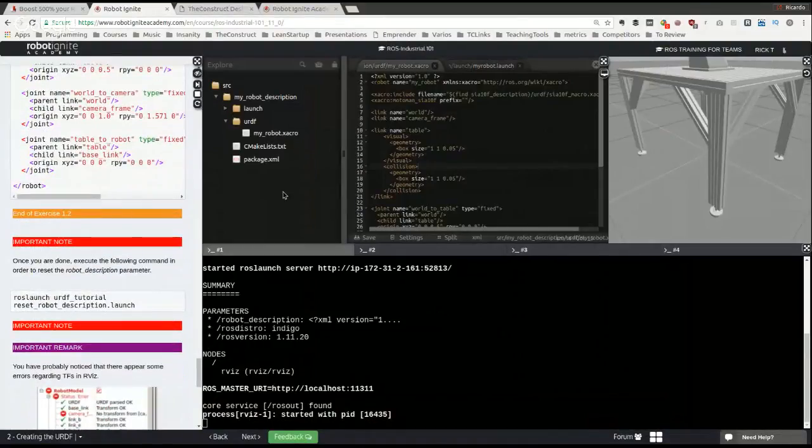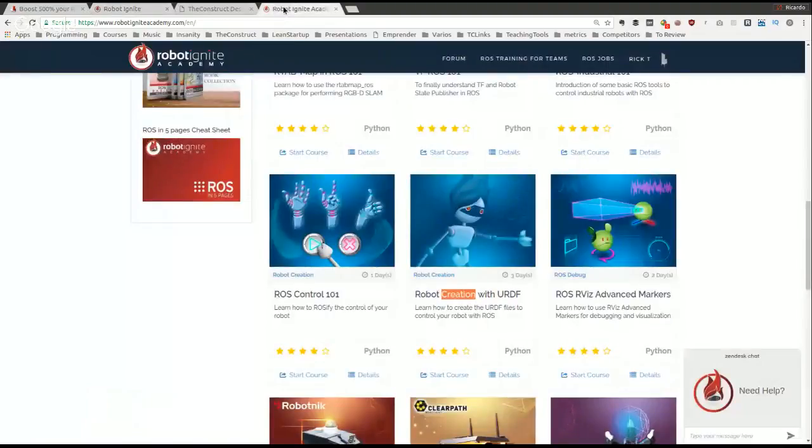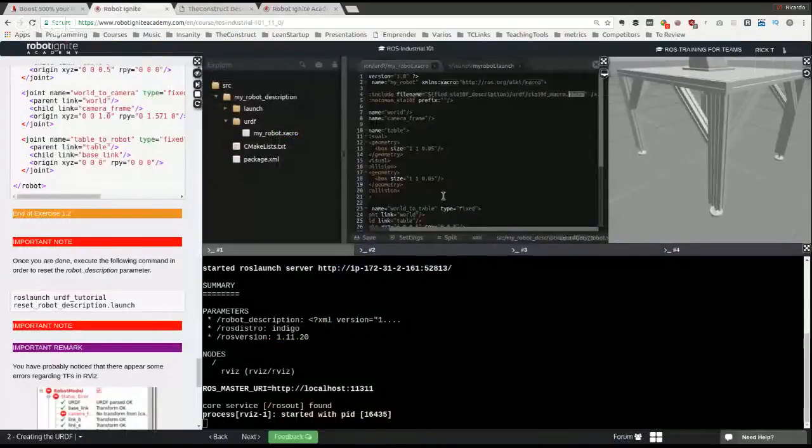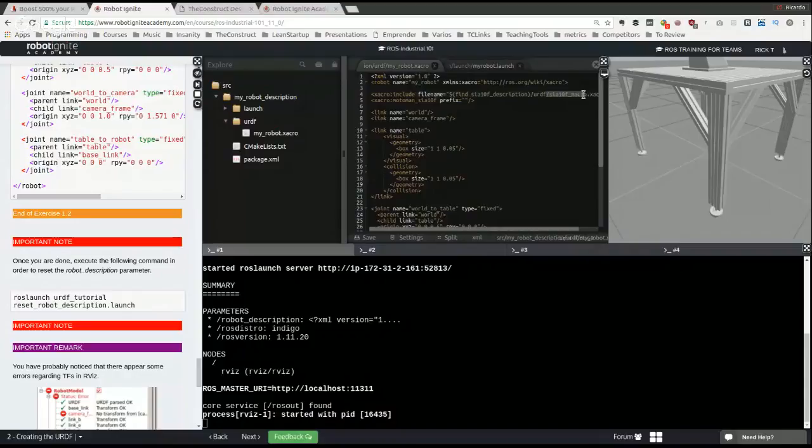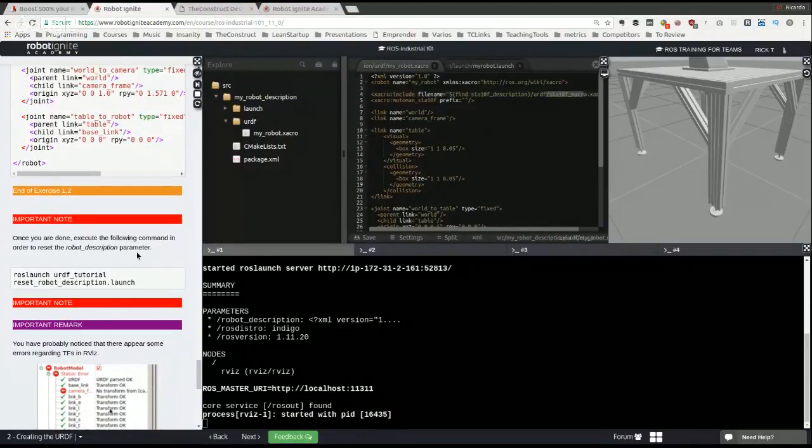Then, of course, the most important part here is about creating this Xacro file. So for that, again, let me tell you that maybe it's interesting for you to create this URDF. Also, for most common and popular industrial robots, the URDF has been already created, like in this case. So we did not create this model. We took it from the internet, where it is already available.